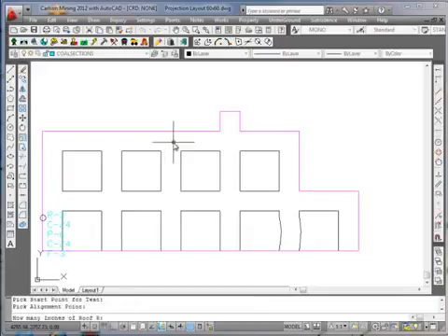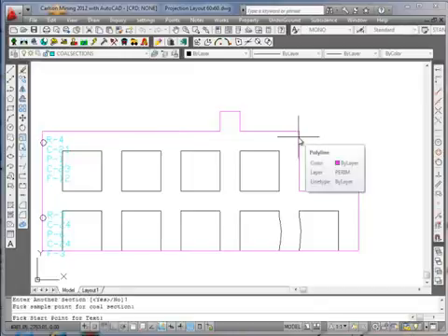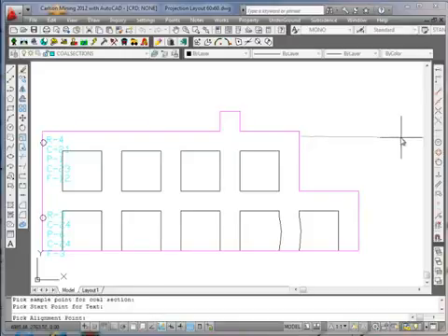and then we'll draw the text in that direction. So then again we'll come through with so much for the roof, 21 for the upper split, 1 for the parting, 23 for the lower, 12 for the floor, and we'll do another one, and we'll come over this side, pick here, and we'll set the text just to the outside, and we'll say there's 6 inches of roof, 30 inches of coal, 3 inches of parting, 25 inches of coal, and 2 inches of floor.